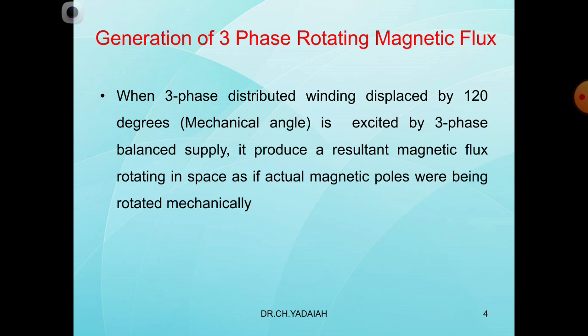Hence how to overcome this? By using the damper winding. Damper winding is copper strips inserted in the rotor pole shoes. The copper strips are inserted in the pole shoes, and both sides are short circuited, just like the squirrel cage rotor strips.